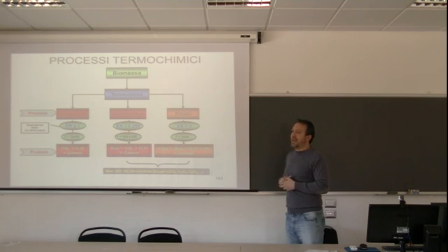In many cases, the owner of the plant prefers combustion. We were mostly focused on the feed to the gasifier, like what happens before it goes into the gasifier, because in the gasifier it's straightforward, you can't change much. But before that, in all the operations, we changed the moisture content, we bought dry feed, introduced different moistures, different mixtures, then pumped it at different pressures, different temperatures and everything. It's really complicated. We had many accidents in that.